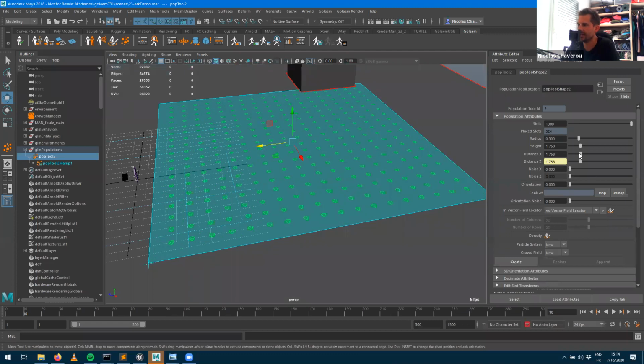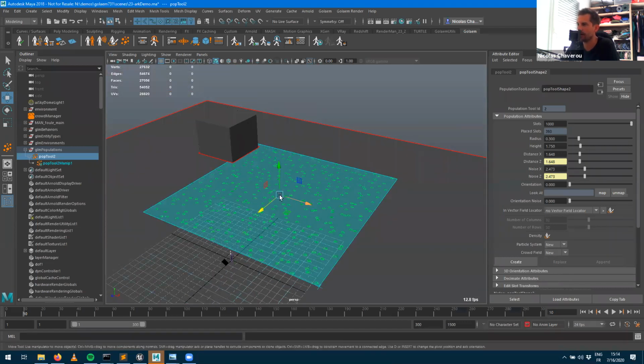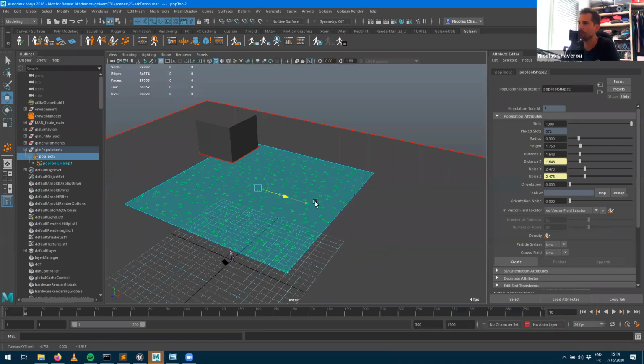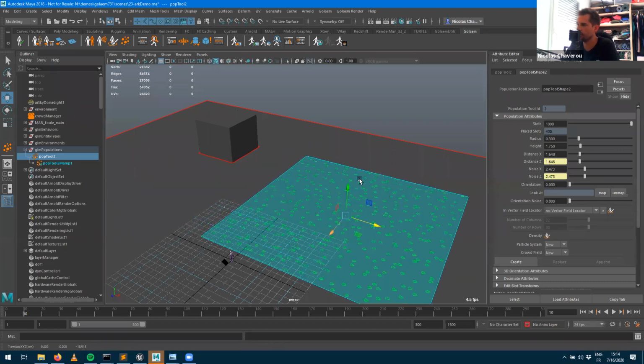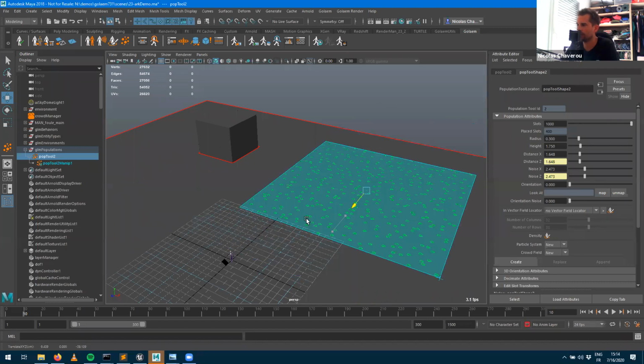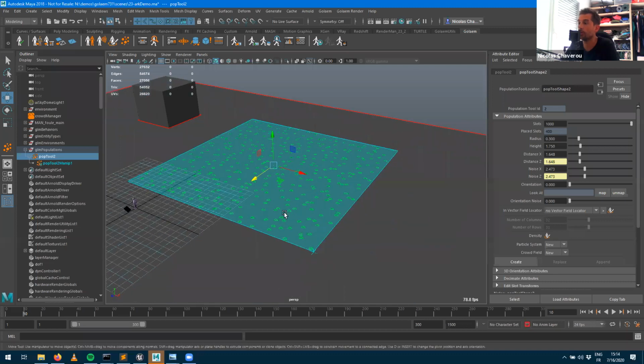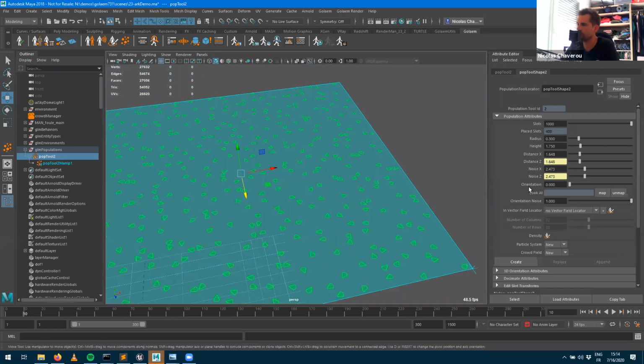So when I change the distance, I end up with a kind of grid shape, which I can noise to have something more organic. And something really nice about having already the environment defined within the scene is that when I move the box, you can see that I'm never going to populate characters which are in a forbidden zone. So I always make sure that I'm not going to populate characters where I'm not allowed to. And the same goes with the borders. If I get that closer to the border, you can see now the characters don't go out of it. I can change the orientation, noise the orientation. And obviously here I'm using controllers, but if you want, you can paint this with textures to control the orientation, the density, or whatever you want to.